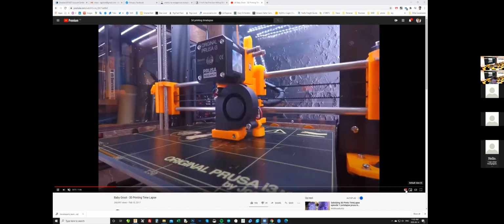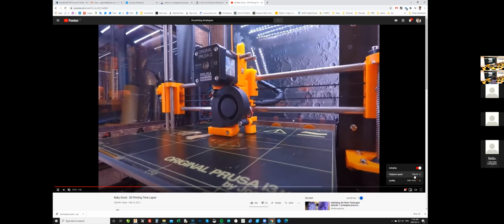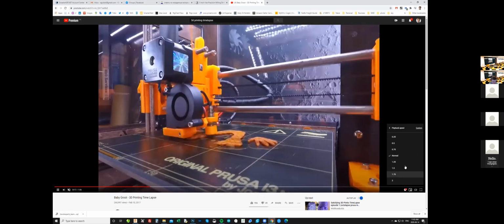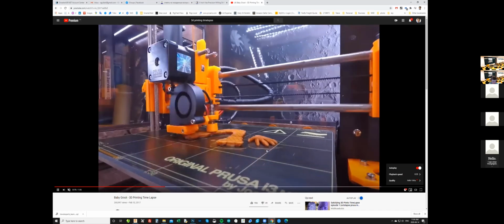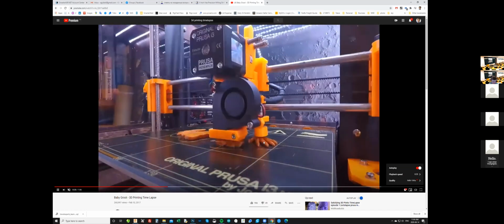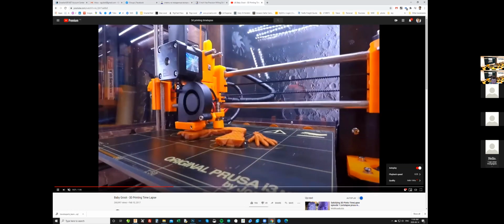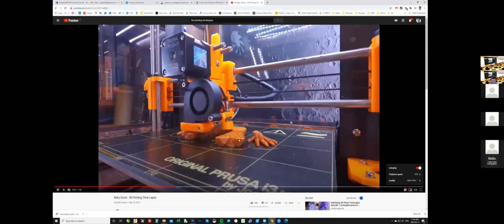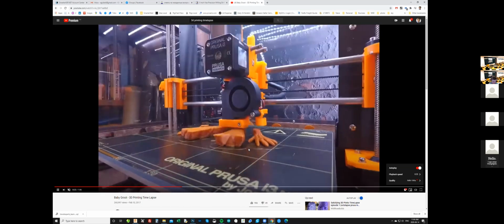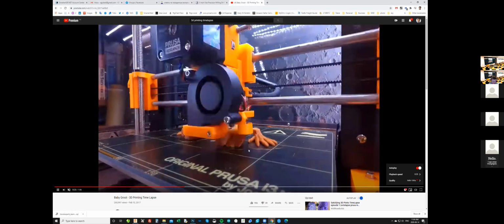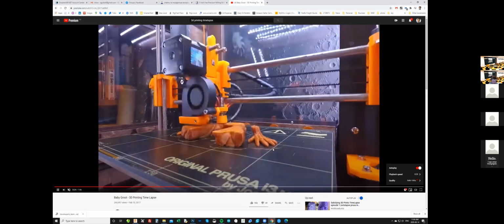So this is called a time-lapse video. So it prints, and they play it back at super high speed. So let me just slow it down. So you see, every single layer needs some sort of underlayment to be put on top of. If there is nothing underneath, then plastics just don't have any support and are just gonna fall down on the platform. So you're not gonna get a proper solid shape.